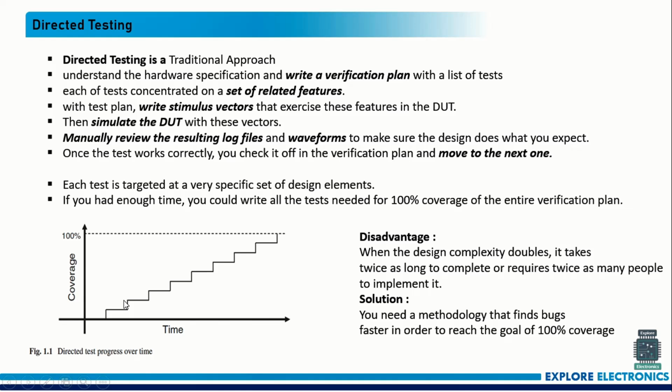Likewise, if you take again the concept of an ALU, addition, subtraction, multiplication, logical and, or, modulus, all those become individual test cases, and completing those takes much time. So the disadvantage is that when the design becomes more complex, it takes twice as long to complete and requires twice as many people to implement it. So that is the disadvantage in directed testing.